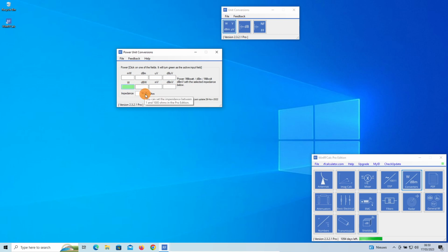If you want to convert power to voltage, an important factor is the impedance base. So well, if you want to do this in 75 ohm, just change the base impedance here. This 1 watt is recalculated to these voltage levels and these dB voltage levels. Right.